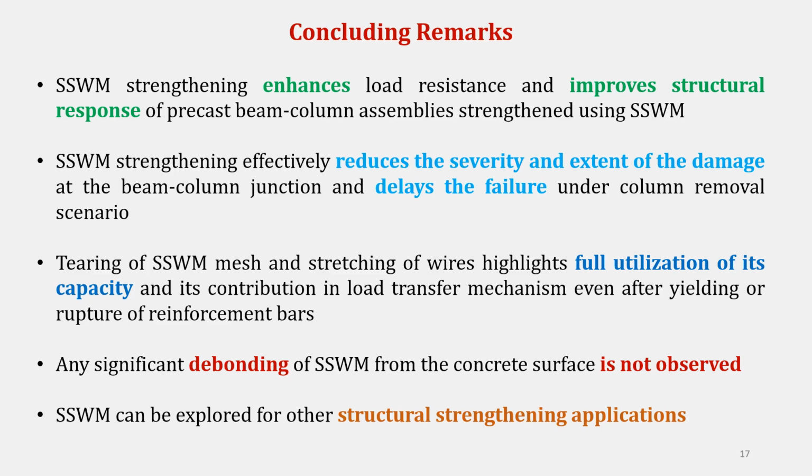Based on the study results, it is observed that SSWM effectively enhances the load resistance of beam-column assemblies under column removal scenario. It reduces the severity and extent of damage around the beam-column junctions and delays the failure. Carrying of load by SSWM and stretching of wire in the mesh indicates utilization of its full capacity and effective contribution in load transfer even after yielding or rupture of rebars. Any significant debonding of SSWM from the concrete surface is not observed. Overall, SSWM strengthening improves the structural response under column removal scenario and can be recommended for practical applications. However, it can be explored for strengthening of different RC elements under different loading conditions to make for wider acceptance.